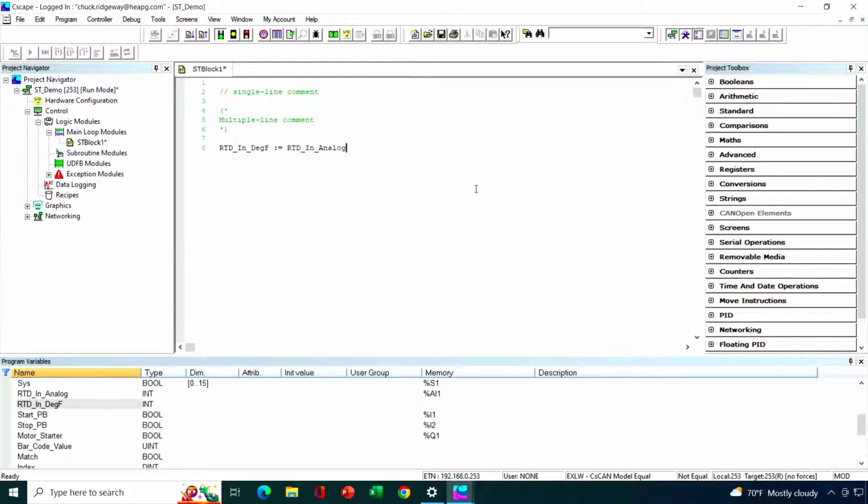So that means that the numbers are overstated by 20. So we need to start by dividing that by 20 to get it down to degrees Celsius. And then to convert to degrees Fahrenheit, we need to multiply by 1.8, or by times 9 divided by 5. And then we have to add 32.